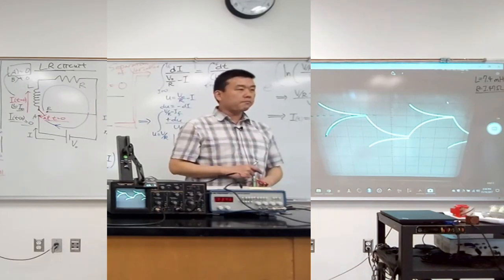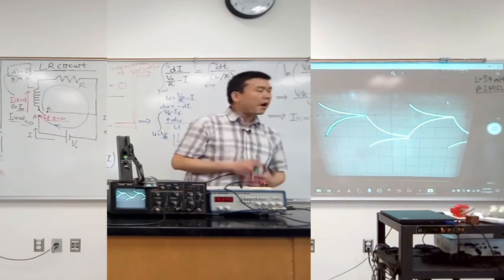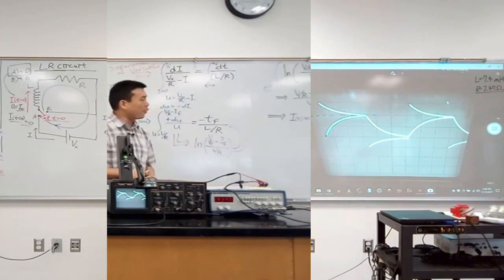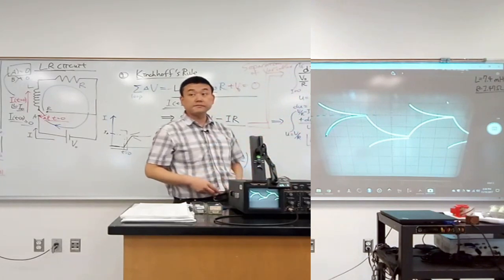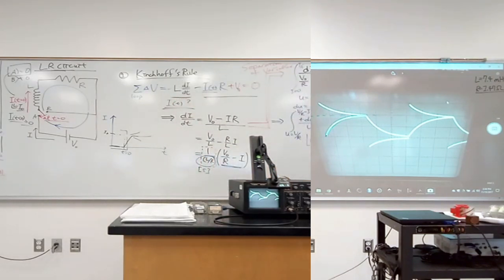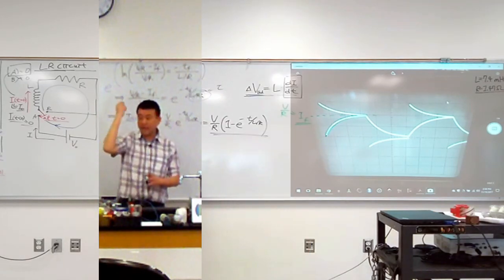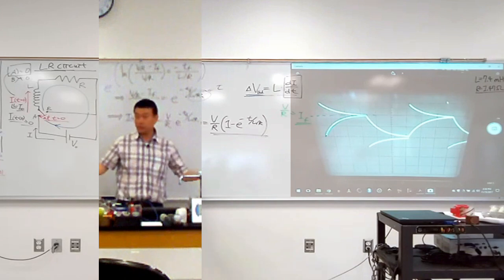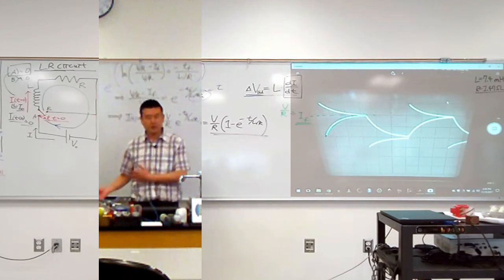But I want you to focus on the property of the inductor itself, not the fact that it's ideal. What about the inductor allows you to ignore it towards the end of this charging cycle? Because that definitely wasn't the case with the capacitor. With the capacitor, when it got fully charged up, it dropped the entire voltage of the battery so that there was no more current flowing. But with the inductor, we are saying almost what sounds like the exact opposite thing.